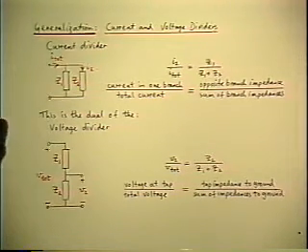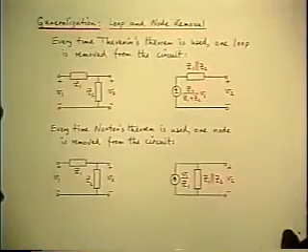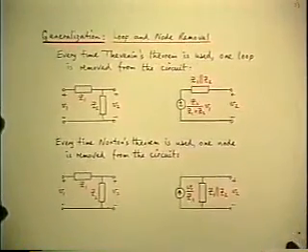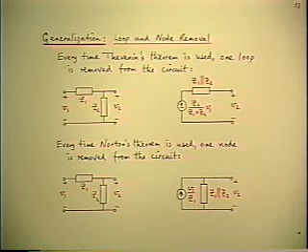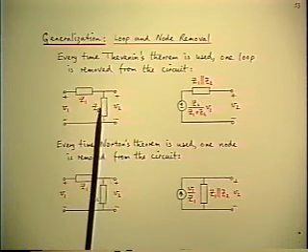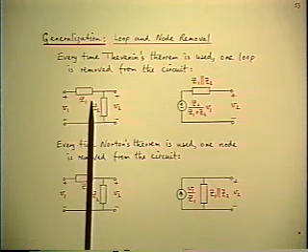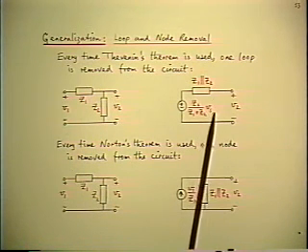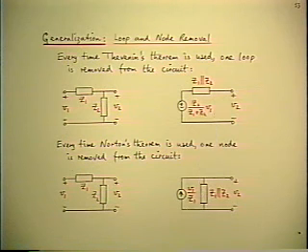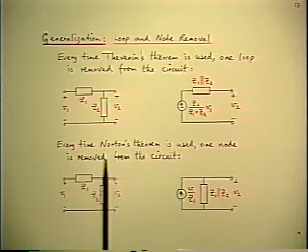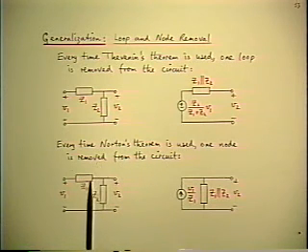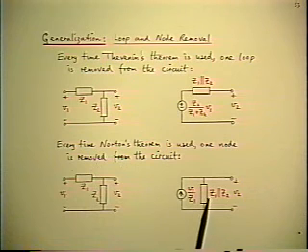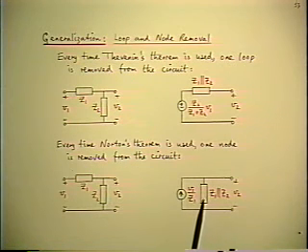That one I mentioned already. Now here's another very useful one that I haven't explicitly emphasized. We've done the example. I said every time you use Thevenin's theorem, the circuit got simpler. It got simpler by reducing the total number of loops by 1. But there's a dual to Thevenin's theorem, which is Norton's theorem. It says you can replace any linear part of the network by a current generator in parallel with an impedance, and you remember the rule for doing that.